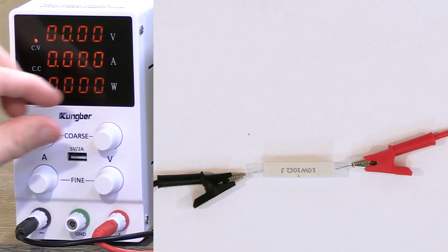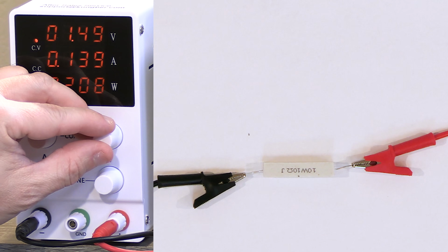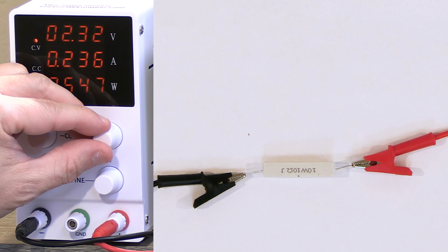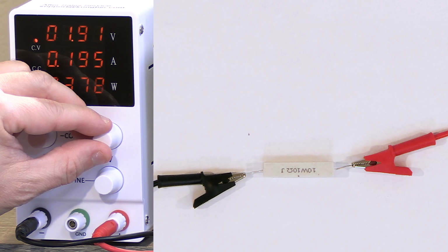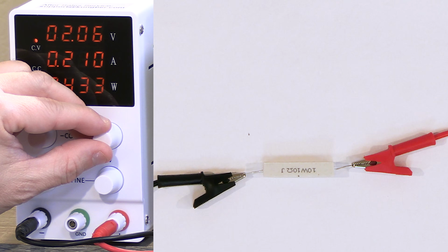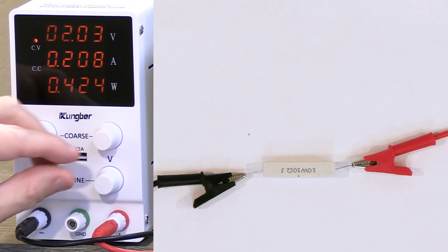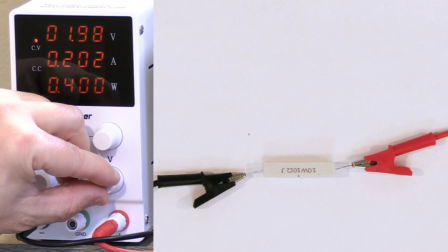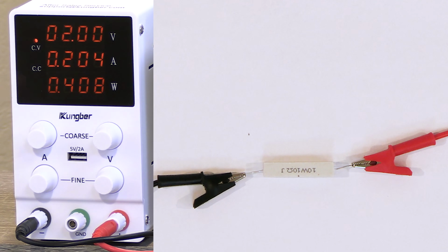We haven't changed anything. We're going to now increase this from 1 volt up to 2 volts, and I've overshot, so I'm going to go down. It's kind of hard to get it exact, so I'm going to go very, very slow, and it looks like I've overshot again. So I'm going to go down, and I'm going to use the fine knob to go up to 2 volts. What do I get? 0.204 amps. Again, not exact, but it's close enough that we know that what we're predicting with Ohm's law is matching reality. This is a nice device because this voltage source also tells me how much current is flowing.